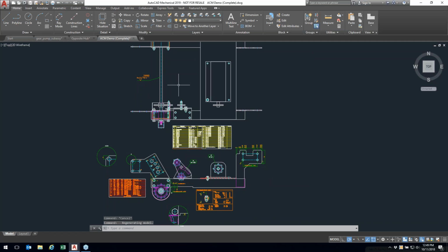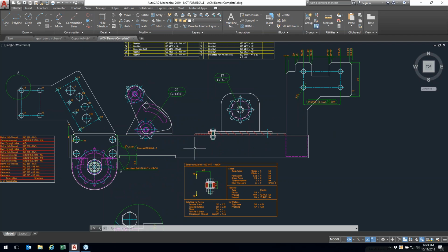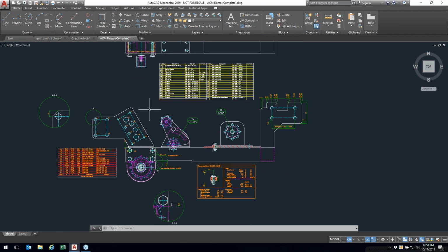So I definitely recommend users get in here and dabble with the AutoCAD Mechanical tool set. The drawing tools are phenomenally faster than trying to draw things by hand using the manual drawing creation methods. Especially if you're doing a lot of view creation or 2D view creation, the construction lines can be immensely helpful. And then obviously the content center, as far as being able to place holes specifically based on fastener sizing, and have it generate the views and be accessible and editable after the fact. All of that is just really powerful functionality.